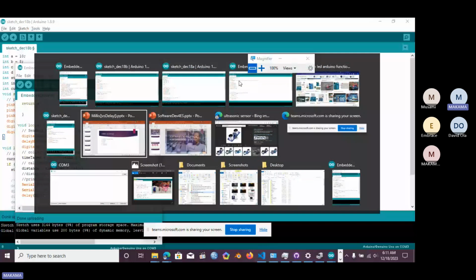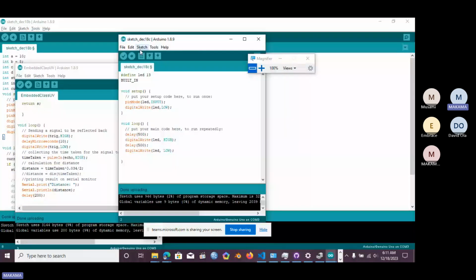So if you call this our pin 13, it will be on and off, right? What if we want to avoid this delay and use our millis function? To do that, I will declare a variable, which is the start time. It doesn't matter what you name it. Let me use small letters. We have our start time.